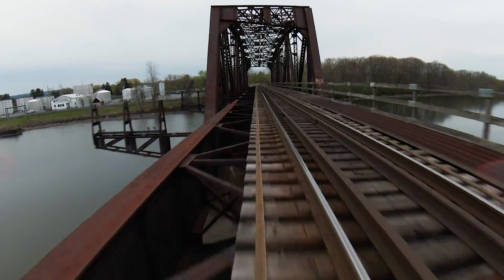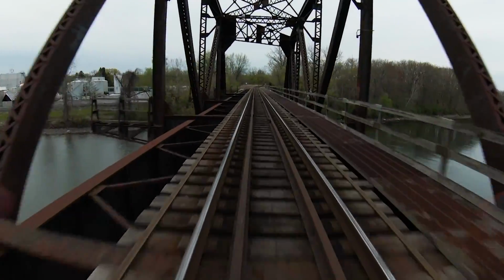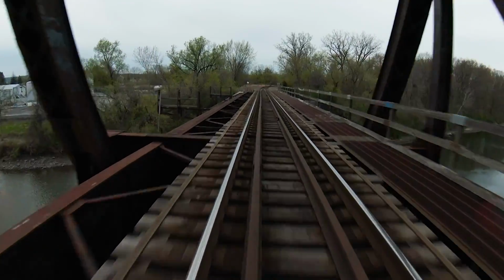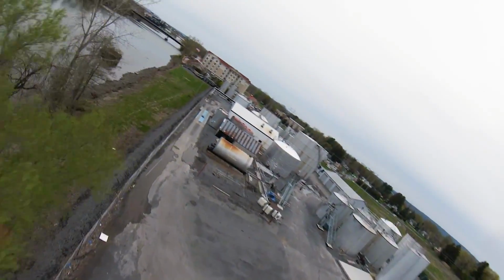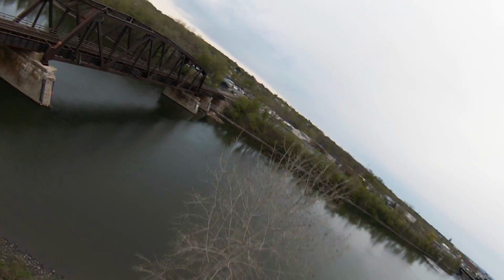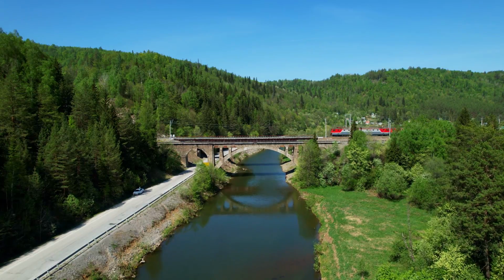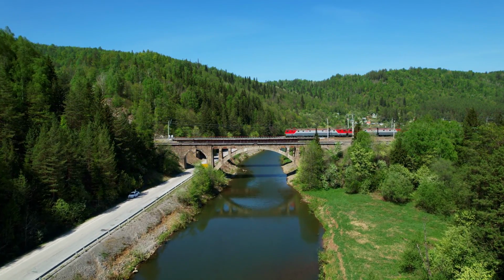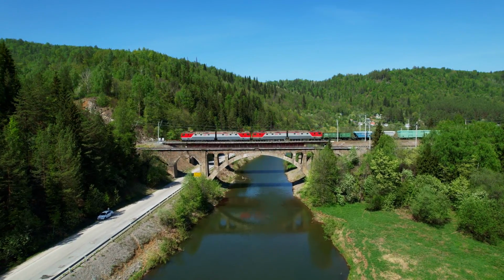Cross and longitudinal timber decks. Monitor the decay, both internally and externally. Maintain the holding down systems. These are the key links between those sleepers, bearers, and the structure below. Plan renewals well in advance. Renewing these assets is a time-consuming and specialist job that requires specific access, especially from below. A bridge isn't just a structure, it's a constraint and a maintenance challenge waiting to grow if you ignore it.